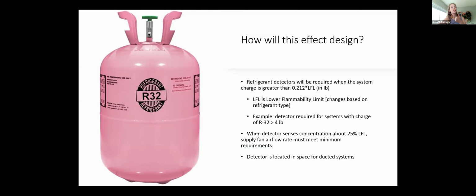The design should list the refrigerant that's being used because these calculations change on the allowable charge based on the type of refrigerant. So you want to see it on the design. The equipment will list it. And then typically, at least our commissioning reports, I know we list the type of refrigerant. I don't think that is a listed specific requirement within section C408, but typically it is provided.